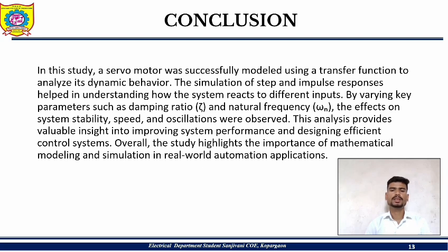Conclusion. In this study, a servo motor has been successfully modeled using a transfer function to analyze its dynamic behavior. The simulation of step and impulse responses helps in understanding how the system reacts to different inputs. By varying parameters such as the damping ratio and natural frequency, the effects on system stability, speed and oscillation are observed.